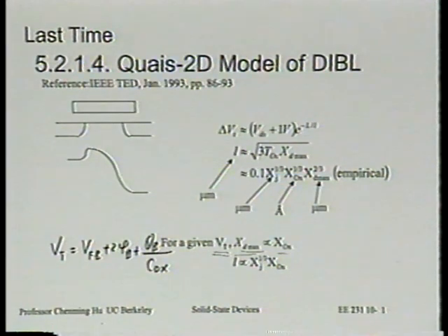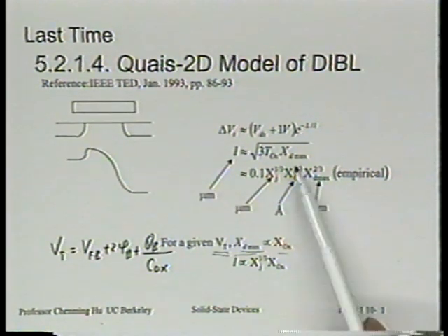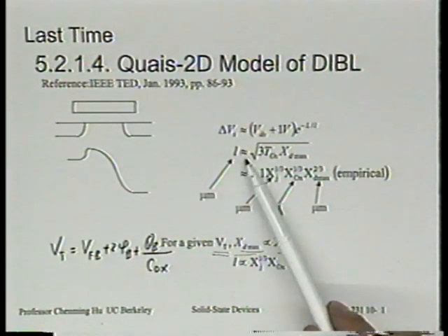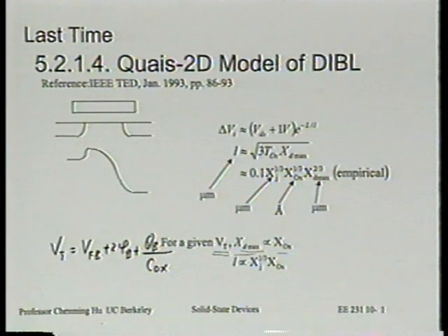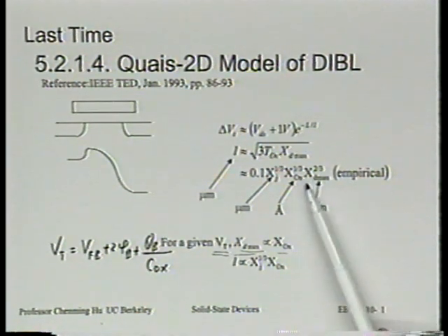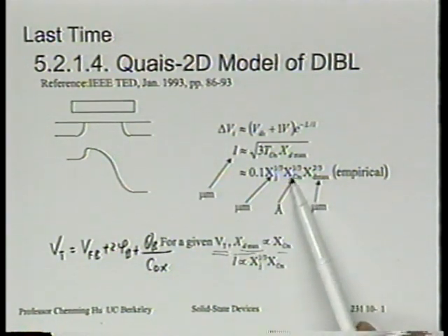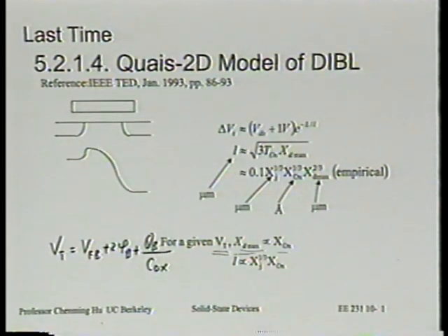So in some way, this result is even simpler, in that XD max and oxide thickness are not independent variables, roughly speaking. I'm trying to simplify the story for you even more. So suppose you say XD max is proportional to Tox, then the decay length is simply what? Proportional to Tox. That just shows the importance of making oxide thin. Clear? If you use the second formula, then you still end up with decay length proportional to oxide thickness and also proportional to xj to the 1/3.